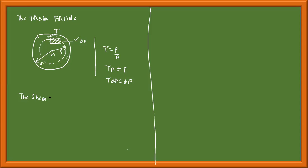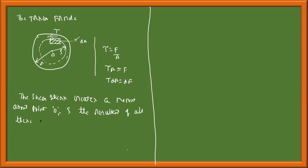Now, I will explain this. The shear stress creates a moment about point O, and the resultant of all these moments about point O is equal to the applied torque T. The shear stress tau, which is acting like this, creates a moment about point O.